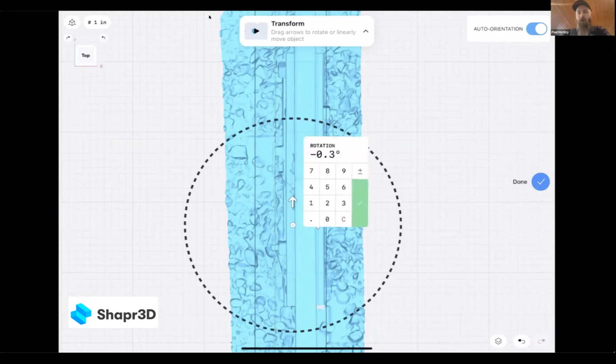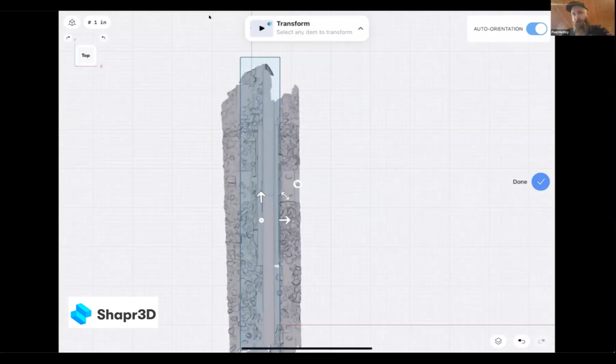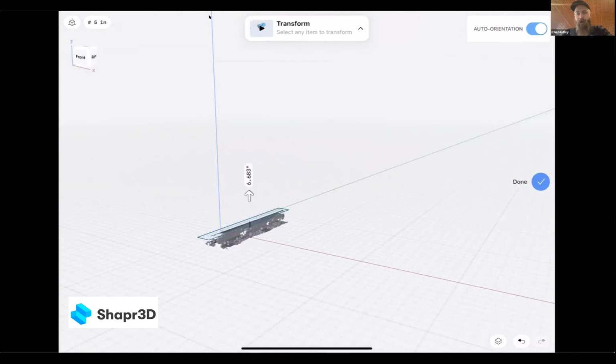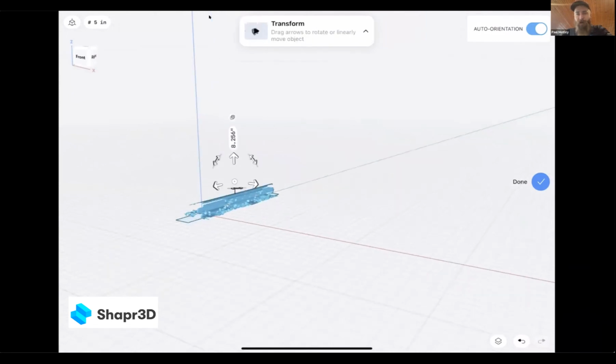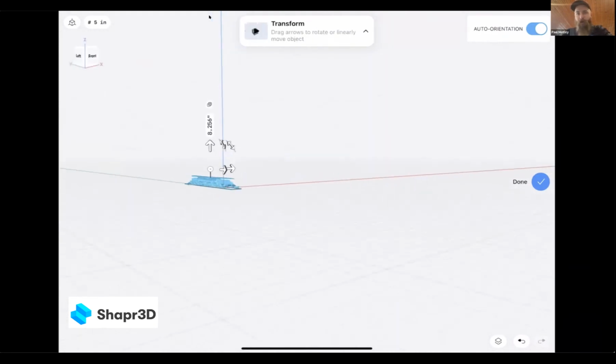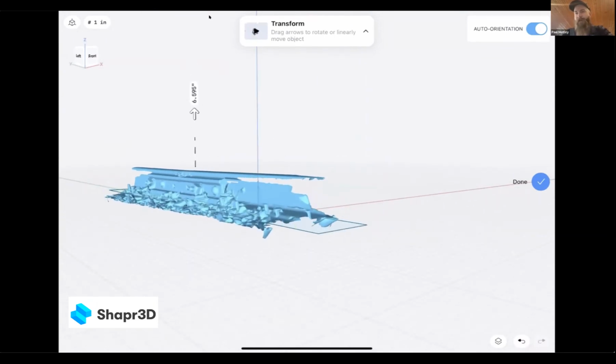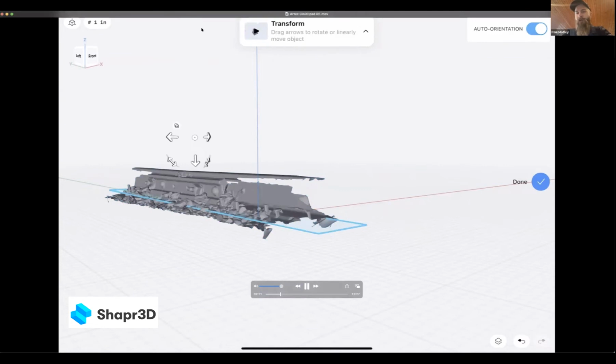While we can go in and create accurate 3-point planes inside of this software as well, what I found was that if we just build out one simple solid body initially, we can use that as our reference point to more easily sketch on our part and keep everything true in a CAD fashion.